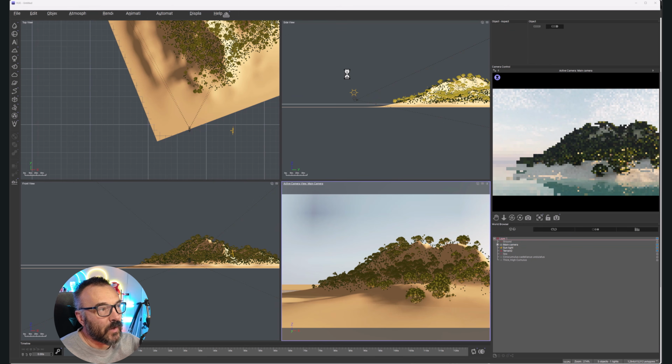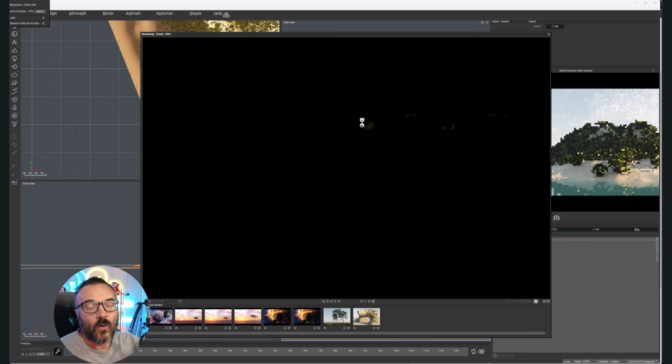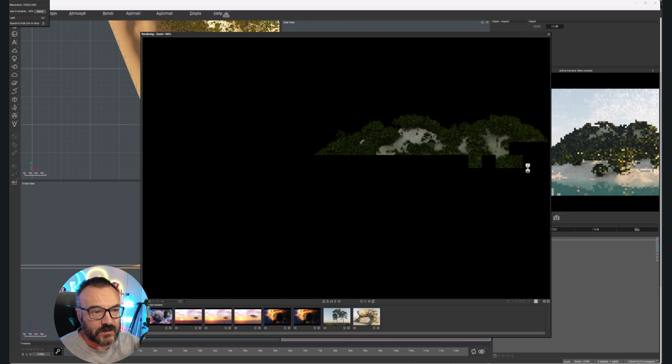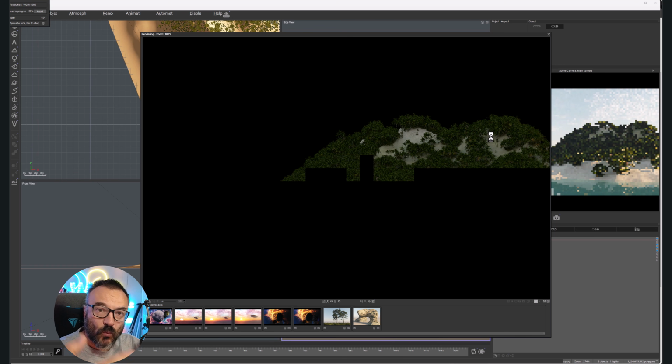And now to render, we click on render. Render may take different time, depending on your computer. It's called bucketing render. You can see it's like a squares render. You will have first a pre-pass render, and you can see right here this is calculating the lighting and everything, so it does one pre-pass.